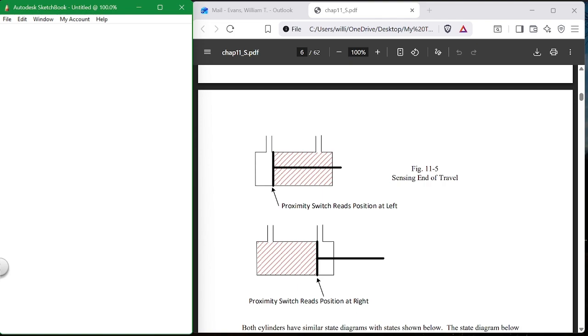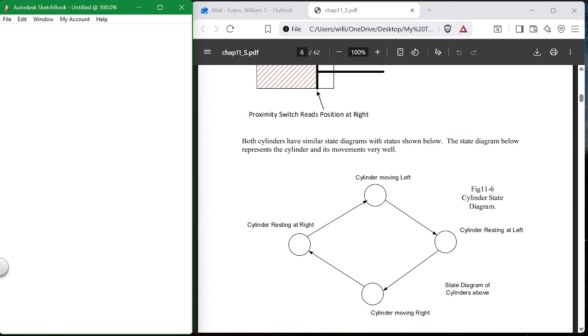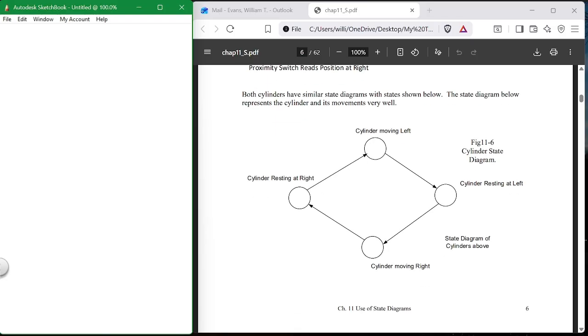When I see a cylinder like this, what I typically do is what I've done in the past. If there are two outputs in the program for this, I will stop the program, force one on, then turn it off, then force the other one on, then turn it off, then force both on and turn them off, and see what happens. Because it can be anything and everything how these operate. But again, I'm not trying to say how it works, just that this is typically how they work.